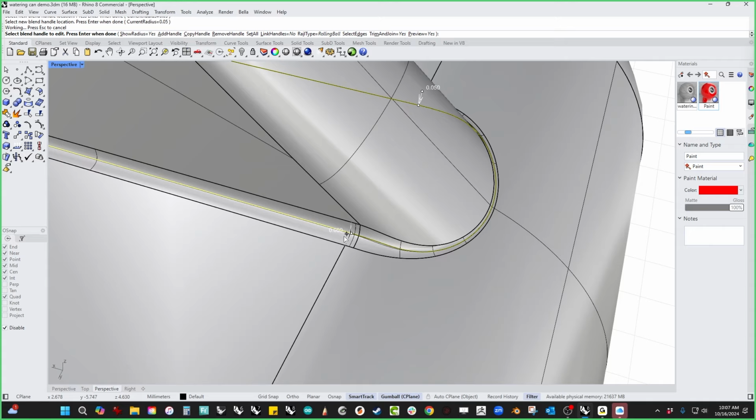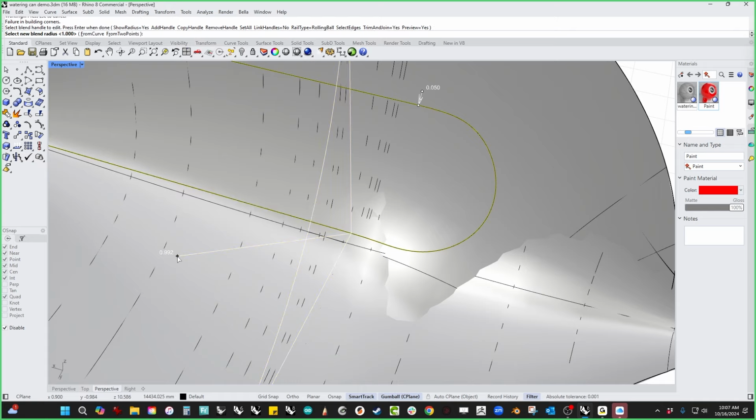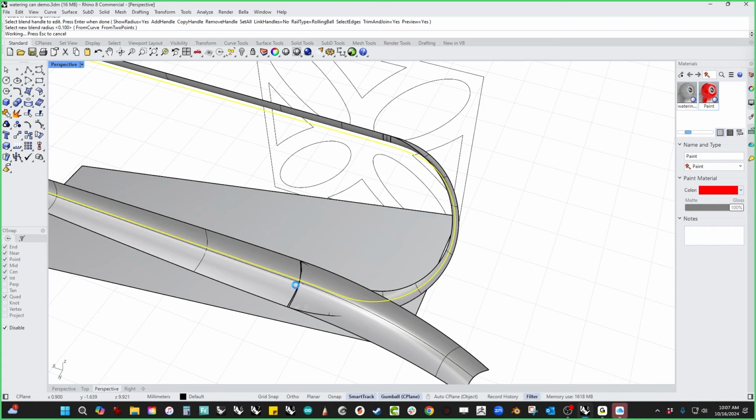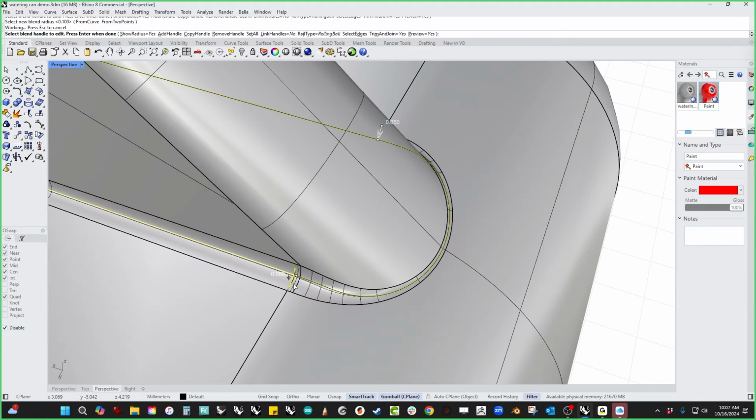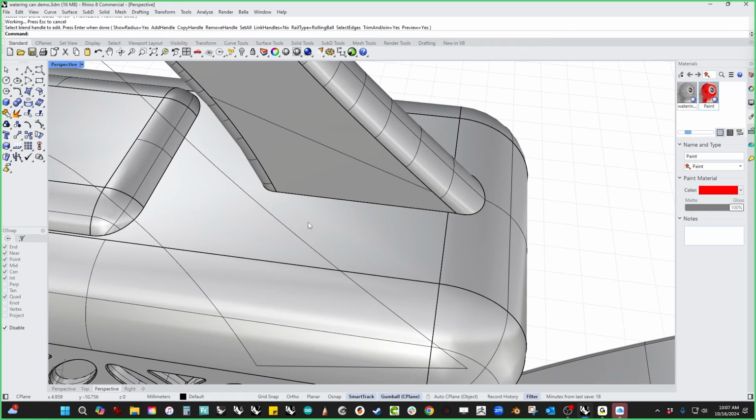So if I take this one and say 0.1, oh, I did the wrong thing. 0.1. Rhino's being kind to me and tolerating this kind of ham-fisted nonsense. Let's drag it down and see if it comes together. And if this doesn't work, 0.5, 0.59, this might be a situation where actually a pipe trim makes my life easier. So I think I am going to just go ahead and pipe trim this because that's not entirely giving me what I want.